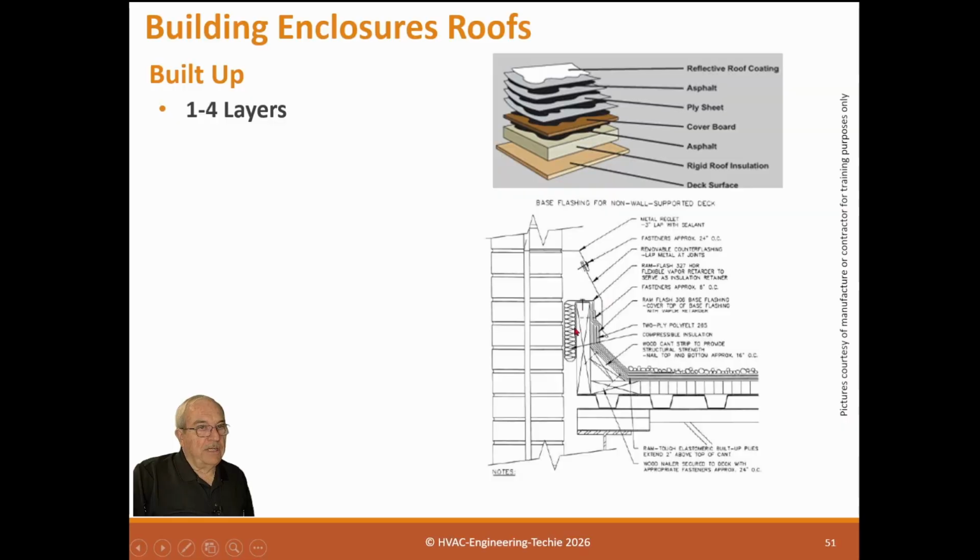So this must become airtight, and that is a problem because most roofing guys that put this in there just shove it in there. They don't pay attention to having gaps, not sealing the corners. So this is problematic. You can leak a lot of air out of an expansion joint, even though it works perfectly well for water. It doesn't necessarily work for air.